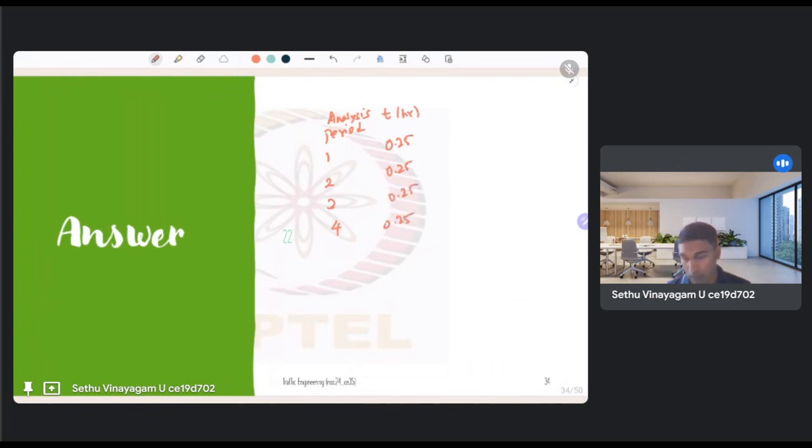Okay, so what we know is the demand is given to us. The demand is in TPC per hour, through passenger cars per hour: 645, 637, 649, and 657. The capacity for the lane of the intersection is constant. Capacity will not change. In the same unit, it is 625.